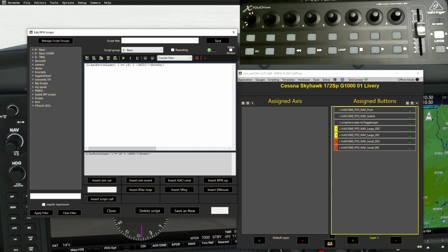Remember, it's really a music device, so it thinks that you're sending a note, but you're not. You're just sending a 0. And we're sending it over the global channel, and that's every single device is listening on channel 1 for commands, and then it only responds if it's got the right number, if it's a number 7 in my case, and I'll show you where you find that later on.